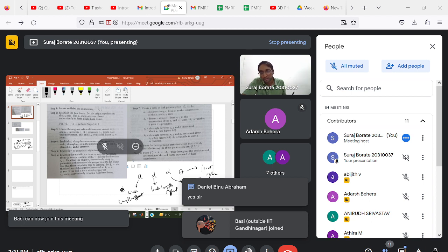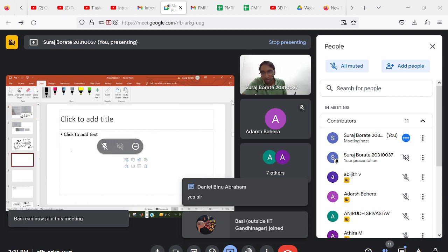Now why such names as twist are given is because, let's say I have this kind of shape or some kind of link. The z axis is in this plane and the other z axis is out of this plane. So there is some angle between the two joint axes, and if I find that angle, then that is nothing but alpha.